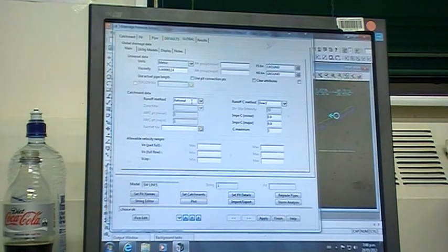Different types of agricultural ground can have quite specific curve numbers, as opposed to the rational method, where in a subdivision we just tend to give it a blanket 0.65 as a C value. The differences aren't exorbitantly different between the two, but the SCS curves are a lot more accurate, incrementally.